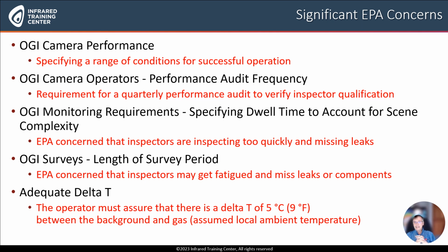Now, what is a dwell time? That is the amount of time that you look at a component at a given angle. And so they're concerned that some inspectors are inspecting too quickly and missing leaks, particularly small leaks. So they're mandating certain requirements that the inspector must meet in order to assure that all the leaks have been detected.